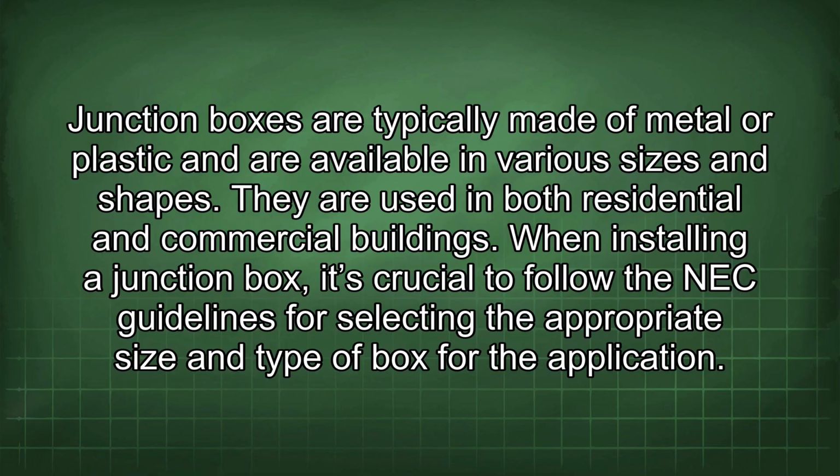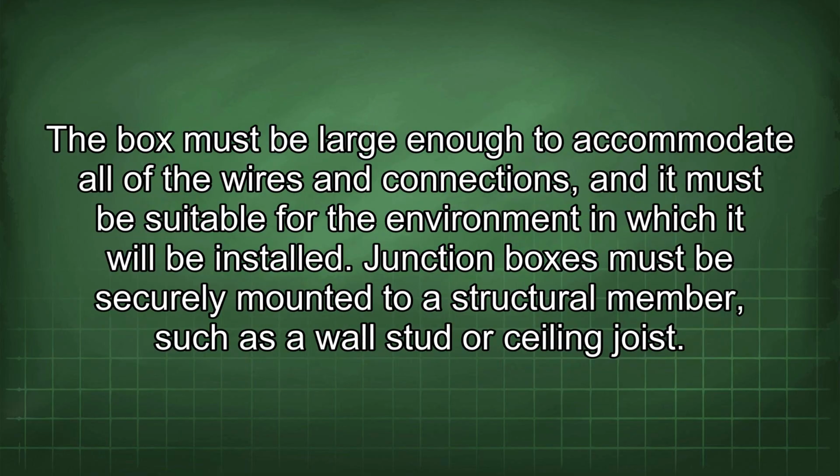When installing a junction box, it's crucial to follow the NEC guidelines for selecting the appropriate size and type of box for the application. The box must be large enough to accommodate all of the wires and connections, and it must be suitable for the environment in which it will be installed.